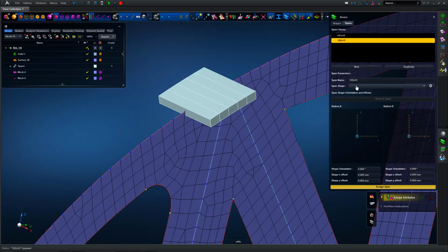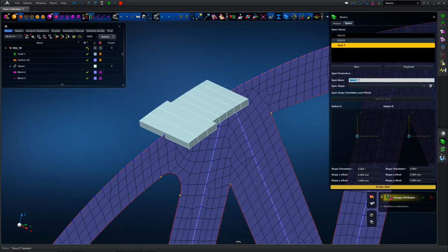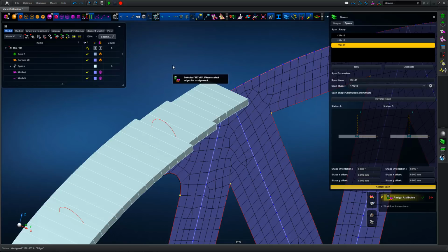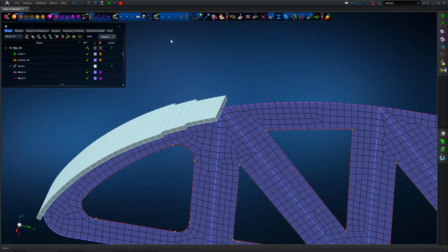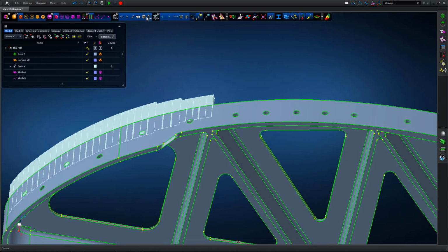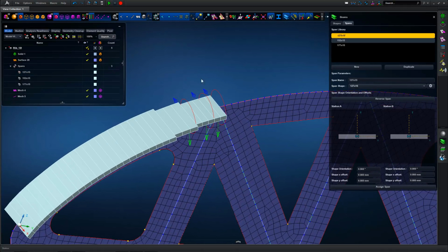And again, doing this for the midsection, 152 by 15, assigning that to the next curve within the shell plane, and again for the second beam span the 3D display is shown, and then finally the 177 by 15 for the widest geometry in the region, assigning that span to the model, and we can see the 3D display shown accordingly. If you compare that with the underlying CAD definition, we can see that there are no offsets defined on the spans at the moment.